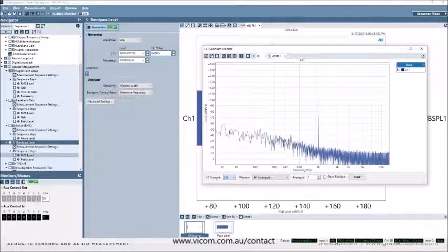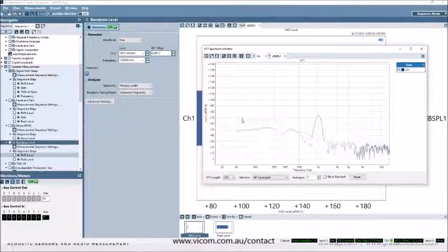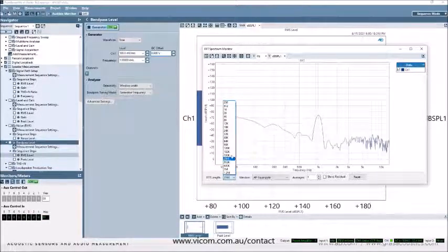At the other end, I could make this incredibly short, and it will update very quickly. But notice that my 1K signal there is really spread out. I have very low resolution. And there is a 0 hertz function in FFT, and that is bleeding over into the upper frequencies. So there's a trade-off in resolution versus time with our transforms.